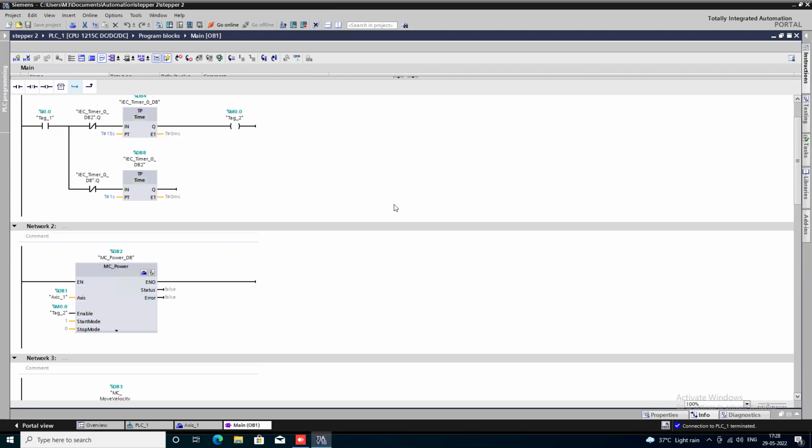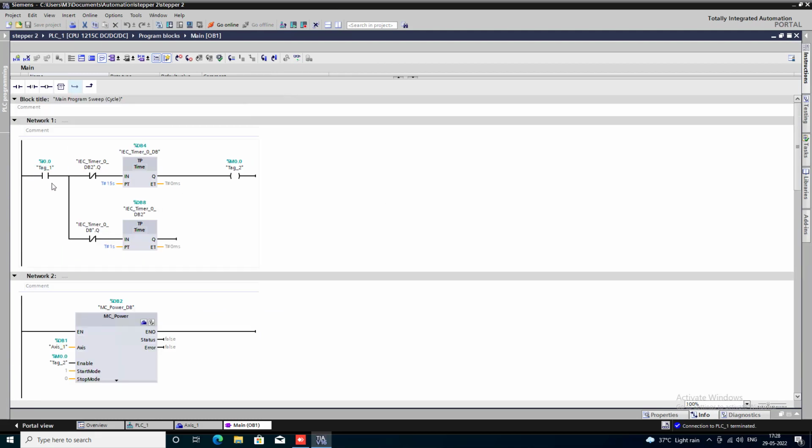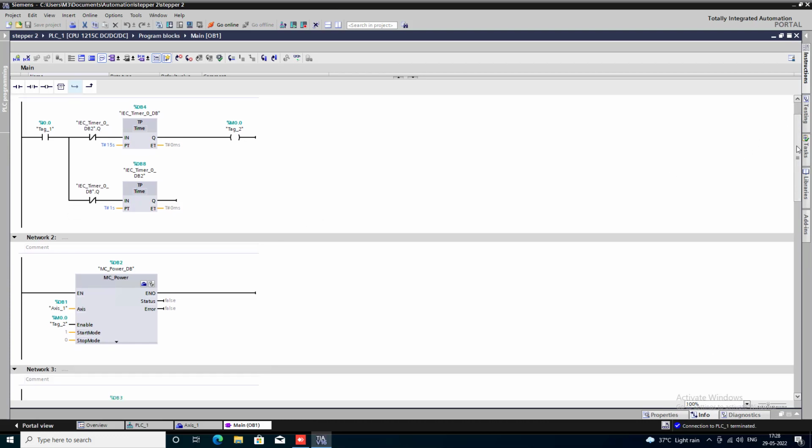At first I took a single input, I0.0, and with that I created a pulse of 15 seconds, and after that, after 1 second, the pulse timer gets reset and M0.0 will restart. With that M0.0 I am just activating my other required tools here.